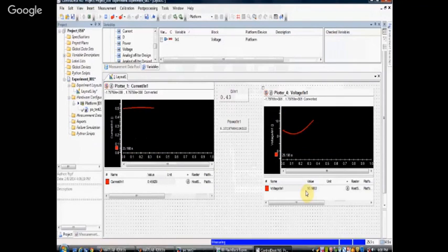Now I've turned on my PV. So now I can see it has gone to 10.7 volts, and my current is 0.5. In the sense, current of the PV panel has also increased, and I can see here some power. 5.2 is the power because the current is 0.5 and voltage is 10. So power is almost V into I. So you can get 5 point something as the power tracked.